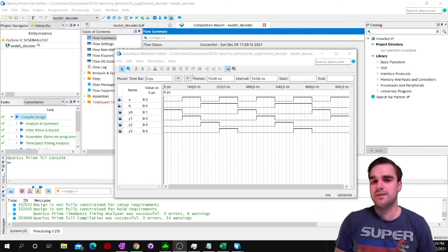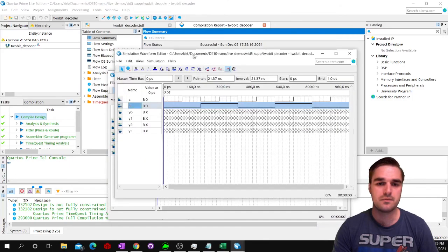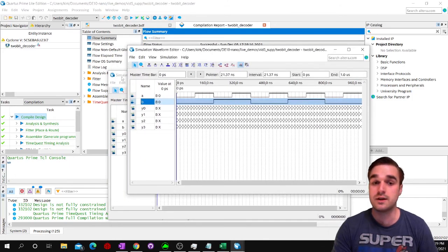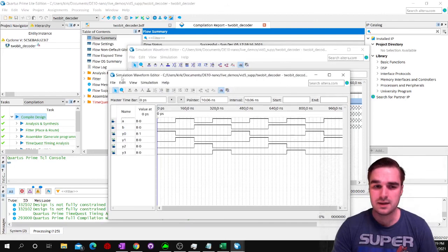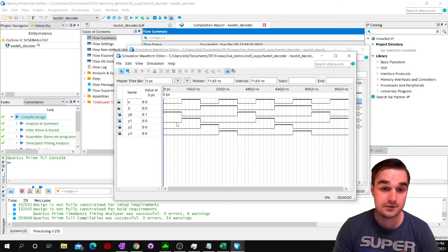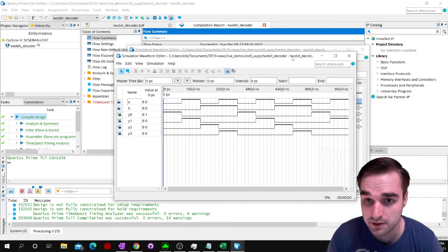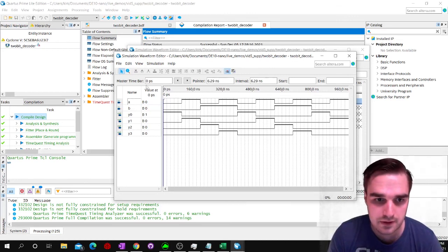It's not that it's invalid syntax. I think the problem is that this vector waveform simulation thing is generating the test bench for you, and because it's generating code, there's a bug, and when it reads your 2 at the start of your module entity name, it thinks that it's the start of a line of code instead of a name or something. I don't even know, but it worked now. Now that I got rid of the literal 2 and spelled out 2, everything's looking good.